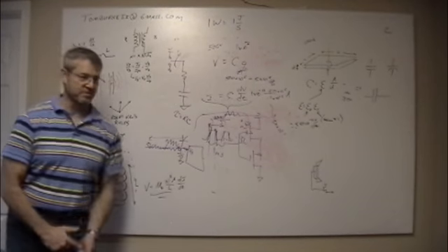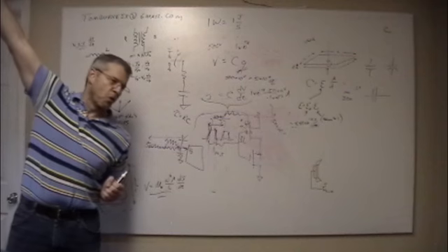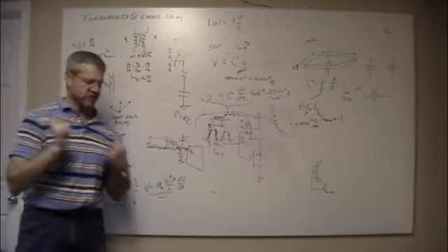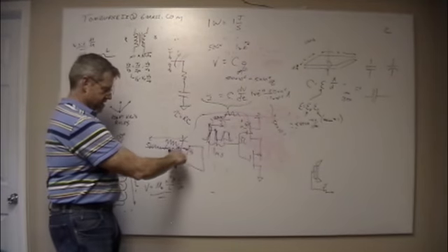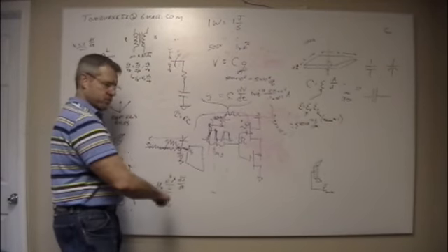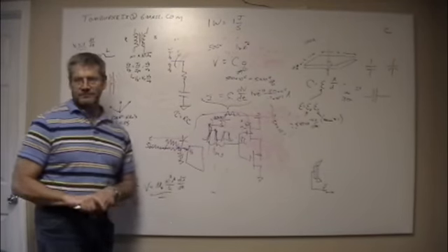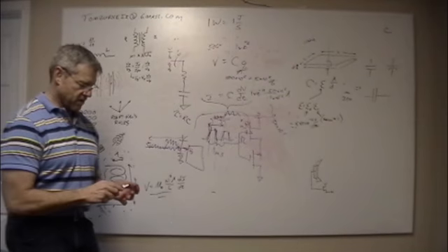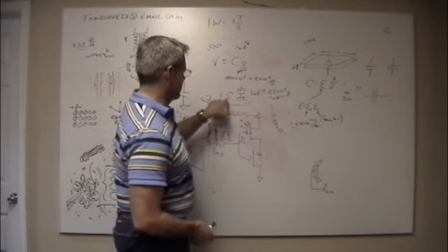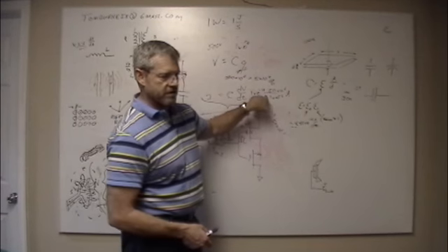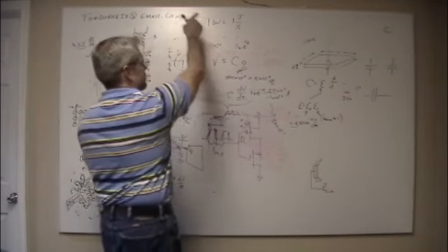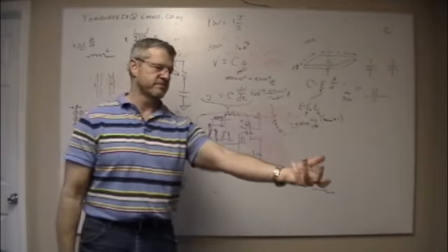The power supply has this giant bucket of electrons that it's just pouring in. You can't make a change in voltage there because the electrons are right there when it needs them. Out here, this guy is making up the little differences. So instead of great big yanks back and forth, it's just little yanks back and forth. And you design your system to say, if I'm going to be at this much current, if I'm running this signal in, it's going to give me this much current. I need this much current for this amount of time. So you work this all backwards and you say, this is how big my capacitor needs to be.